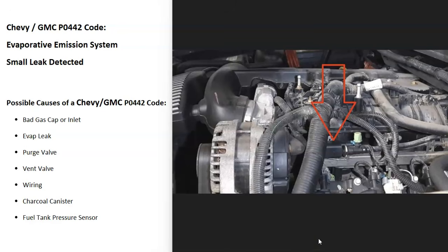You can also go and check out the purge valve. This is going to be located up on top of the engine. It's basically just a valve that opens when the engine's running so all the gas vapors go in and get burnt off. But then it closes when the engine's not running so gas vapors don't go into the engine and flood it out and things like this. It'll be located up around the engine compartment somewhere. It could vary on the exact location. For example, this is a 2012 Chevy Silverado, and the purge valve is located right here. There's some different ways you go about testing the purge valve. I made a video on how you could test these. I'll put a link down below if you need that.